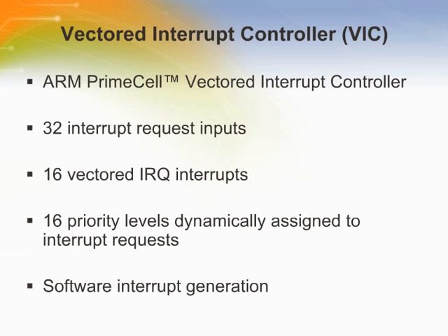The Vectored Interrupt Controller, VIC, takes 32 interrupt request inputs and programmably assigns them into 3 categories: Fast Interrupt Request, FIQ, Vectored IRQ, and Non-Vectored IRQ. The programmable assignment scheme means that priorities of interrupts from the various peripherals can be dynamically assigned and adjusted. FIQ has the highest priority, Vectored IRQs have the middle priority, and non-vectored IRQs have the lowest priority.